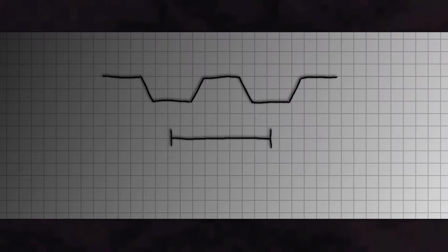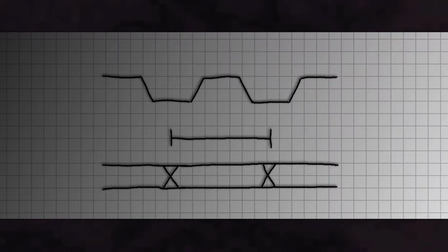Let me outline some of the design choices. As indicated earlier, the whole communication can be decomposed into individual cycles. Each cycle is going to get a resolution of 8 bits, and each bit is going to determine whether or not the line is grounded. Each cycle interval will span from mid-low to the next mid-low of 2 clock periods. That way, the data transitions are as far away from clock high as possible. In theory, this should reduce the risk of falsely identifying a data line transition as a start or stop condition.